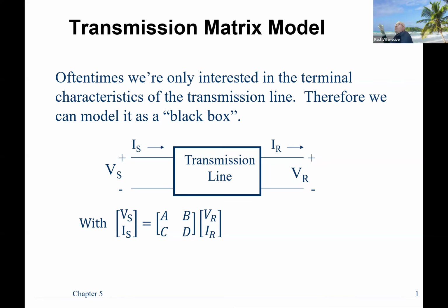Again, the receiving end is what you're trying to control to, meaning that's nominally what you're going to have for your voltage. So 345 kV would be VR. IR would be based on the load that would be expected to be there. And then the source end is just what it needs to be to support what the customer is willing to pay for, based on the system that you, the utility, has designed.